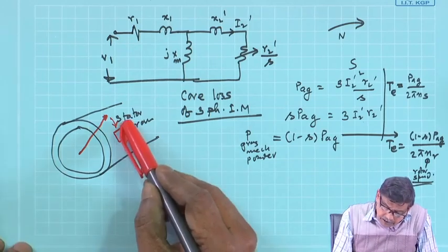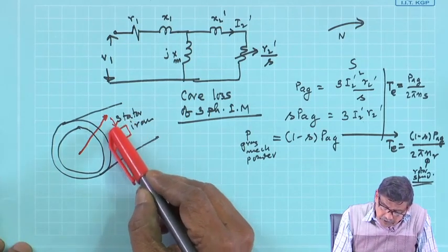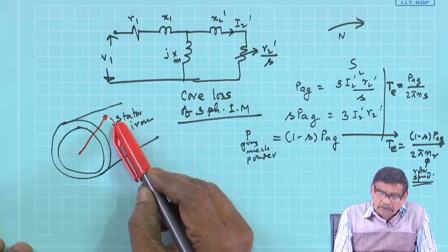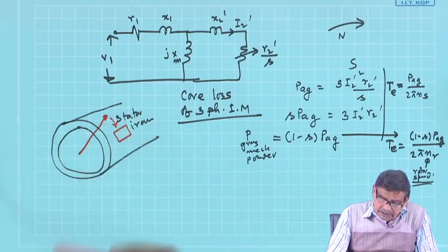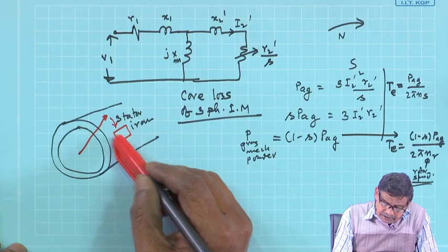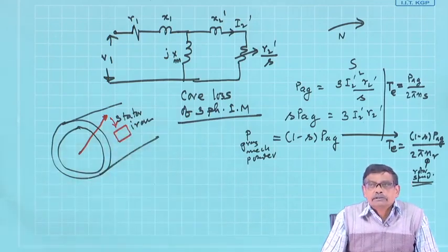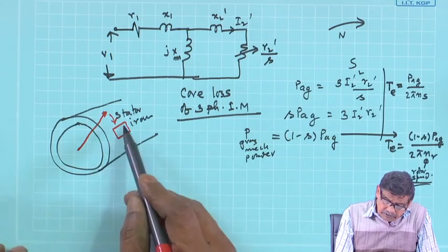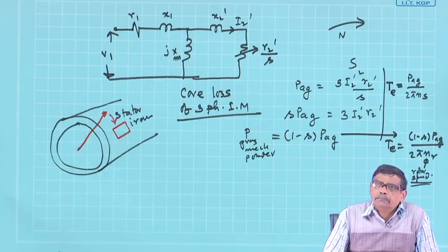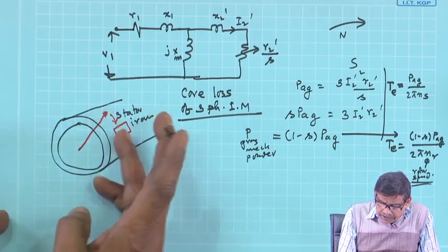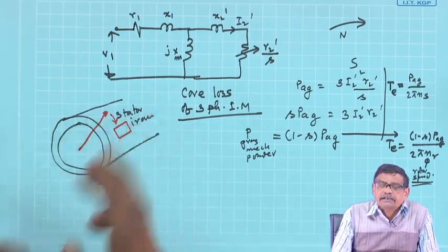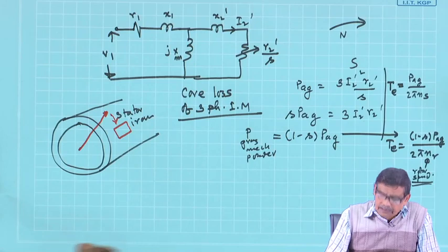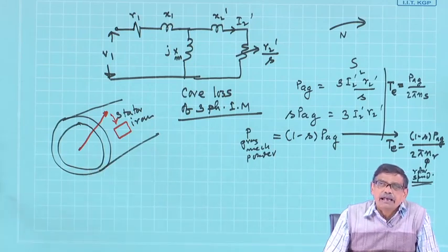and therefore, there will also be current in this loop, and these are called eddy currents, and they will cause power loss on the stator. This power loss will be proportional to, just like a transformer, the frequency at which this flux is cut in this loop, that is f squared, and the maximum value of the flux density squared.